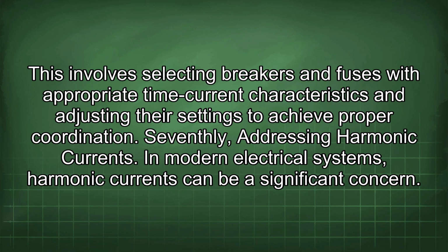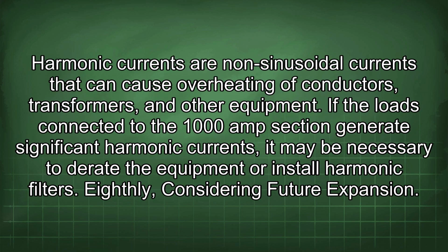Seventhly, addressing harmonic currents. In modern electrical systems, harmonic currents can be a significant concern. Harmonic currents are non-sinusoidal currents that can cause overheating of conductors, transformers, and other equipment. If the load connected to the 1000 amp section generates significant harmonic currents, it may be necessary to derate the equipment or install harmonic filters.